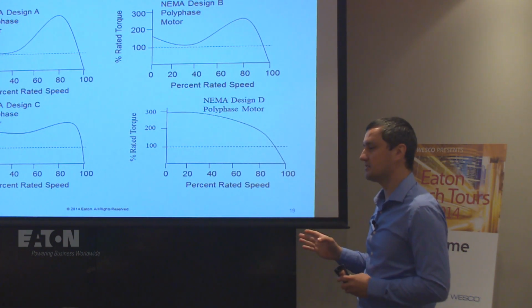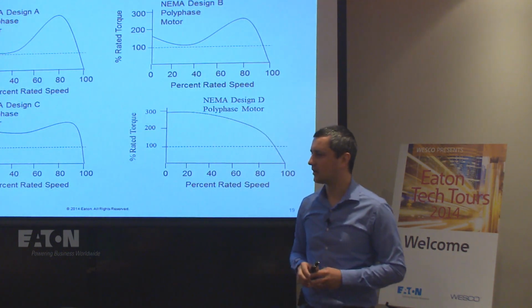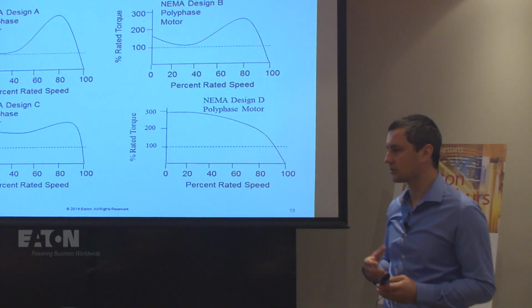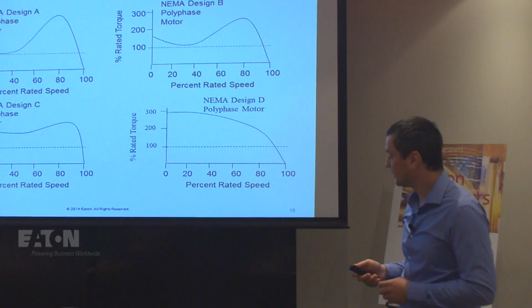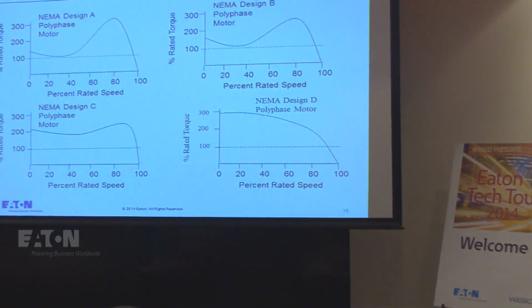Now, with the VFDs, we don't really need this because the VFD can control differently how the motor is starting, so it's going to help with that. So that's another good reason to use the VFD.